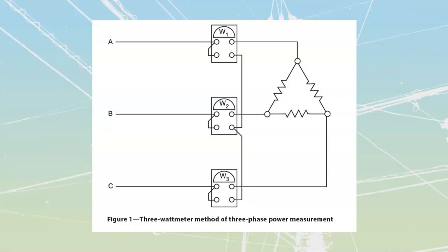Let's talk about measurement methods. If we are dealing with a balanced three-phase system, we have 3 different ways we can measure. We can measure with 3-watt meters, 2-watt meters, or 1-watt meter. The more watt meters we have, the easier it is going to be for us to measure what exactly is going on. It's highly unlikely that you yourself are going to own a watt meter, much less 3-watt meters all at the same time, but occasionally companies have them.